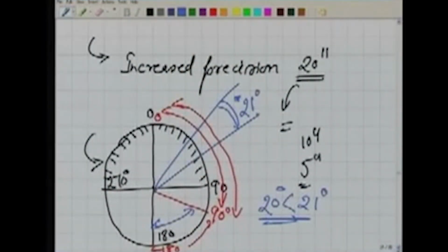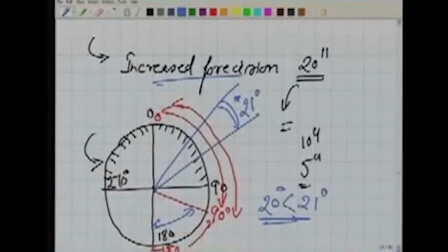Similarly, in the other part, we will observe a smaller angle to be larger. So this might happen. Besides increasing the precision, with the method of repetition we can also eliminate a problem like this. Now how we do it and how we write the readings, we'll do using this particular table here.